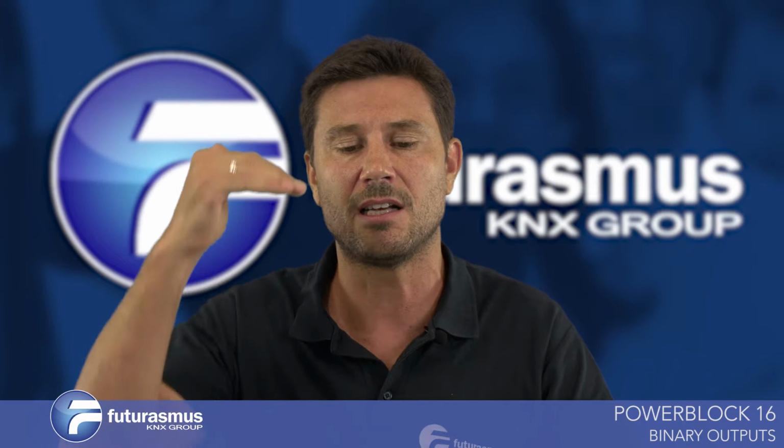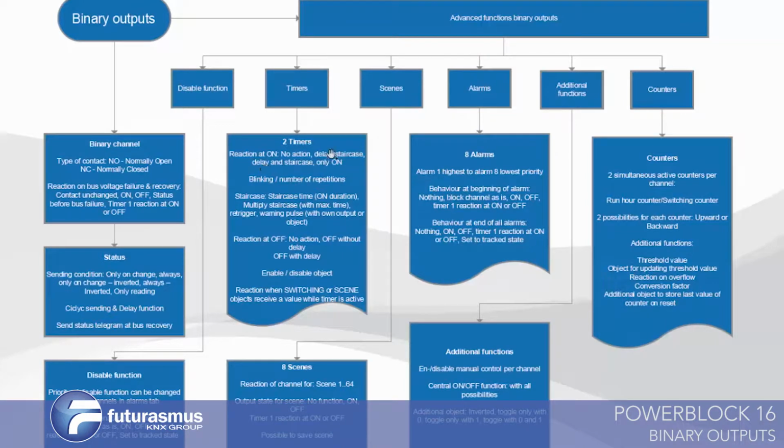So you can decide how important the disable is, whether it has higher or lower priority than the different alarms. That's also very, very interesting. Afterwards, the alarms go away. Okay, so first of all, the alarms come, and depending on the priority, the output switches on or off. And then you can also decide what should happen when the alarms go away.